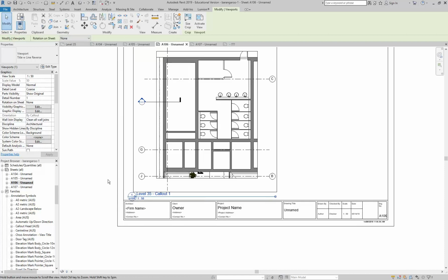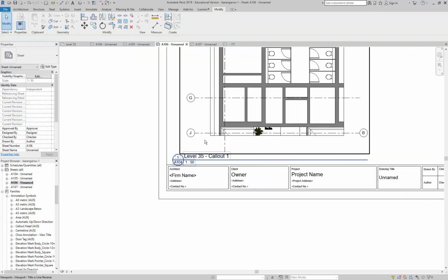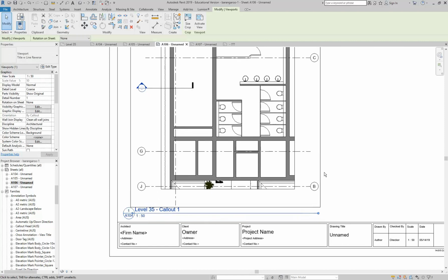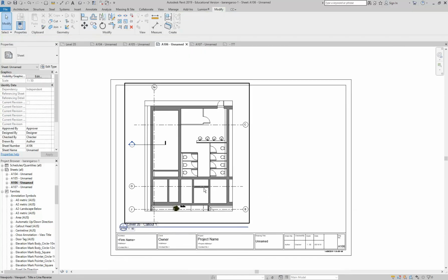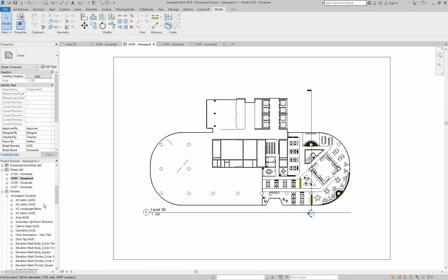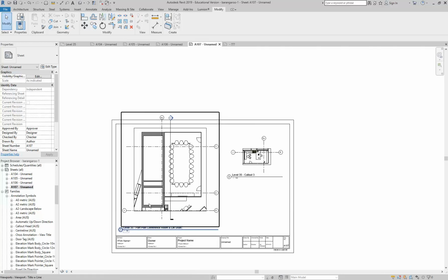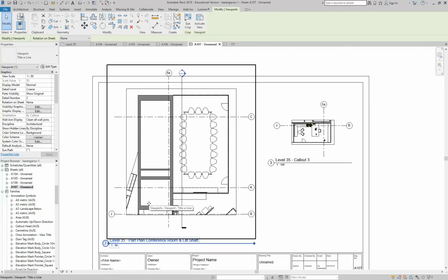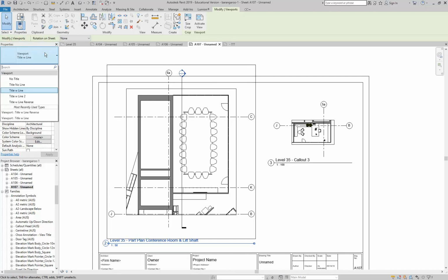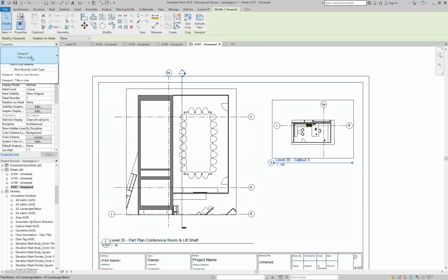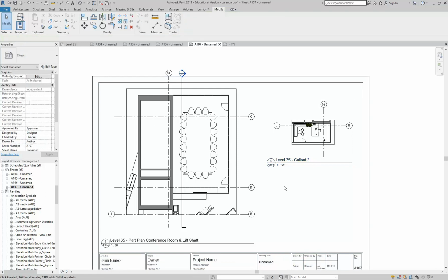So there we are, perfect reverse referencing. And that's a pretty powerful thing if you set that up in Revit, because it's all automated, unlike AutoCAD, where you'd manually be going and checking what view is referring to what. And when you've got a drawing set with over 100 drawings in it, that is a pretty big task. But here you can see it does all the hard work for us.